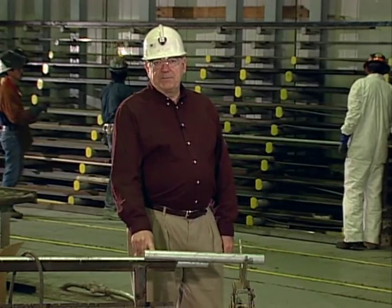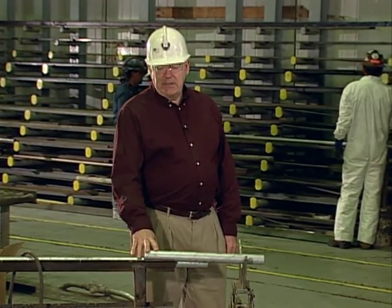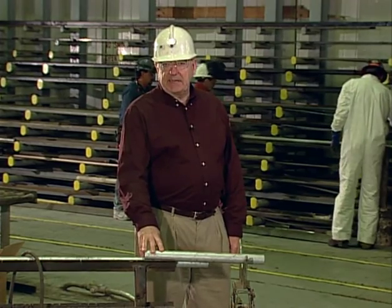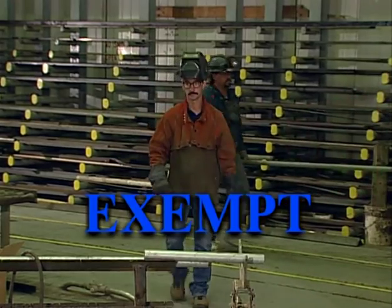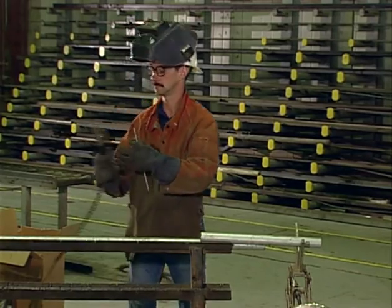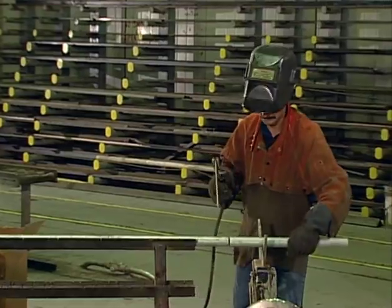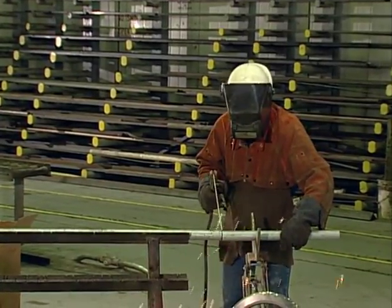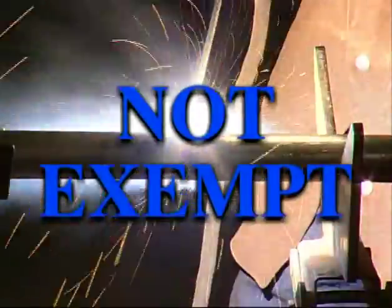This galvanized pipe is perfectly safe under ordinary mine conditions. And under ordinary conditions, it poses no hazard and, as an article, is exempt from HazCom. Does anyone ever weld on galvanized pipe? It happens in a lot of places. Among other problems, galvanized pipe is coated with numerous hazardous chemicals, including lead. When you're welding on it, significant amounts of lead fume are created, among other health hazards, and the pipe is no longer exempt.